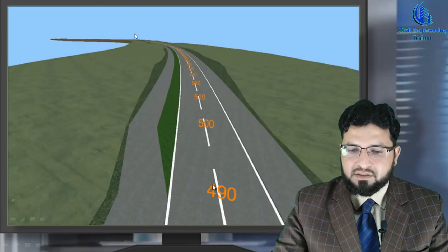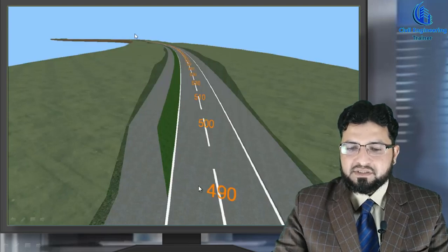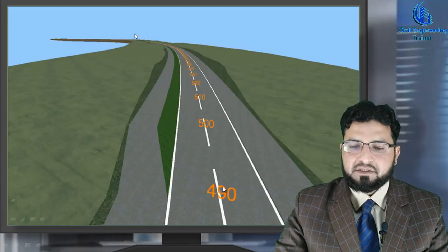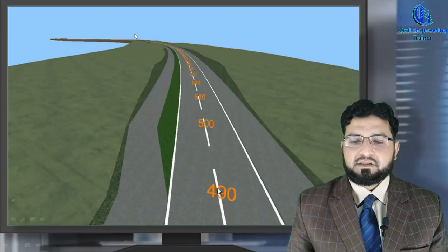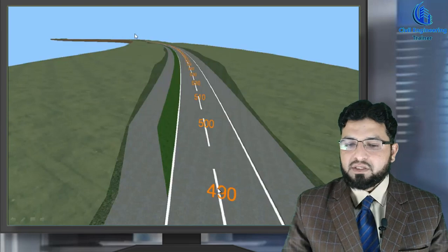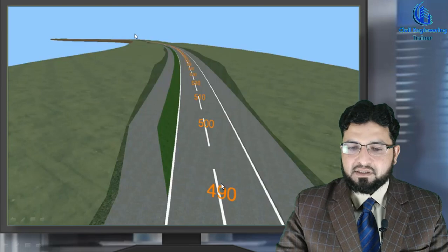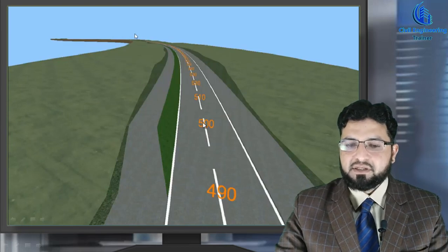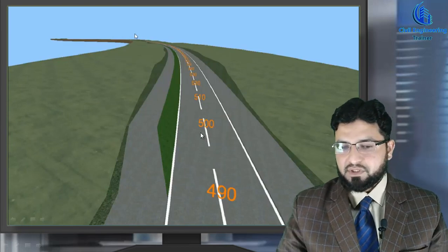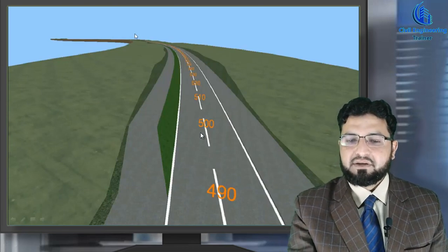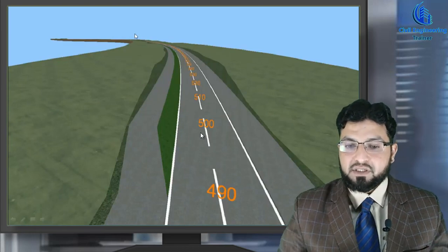Center line. And you can also see some specific values mentioned on its center line. These values are basically station or chainage, okay? Both words are used. What is the main purpose of this? When we give data on site during construction, we give data by the range of station, okay? Suppose we have data about this point like 500 or 510, then we give data on site that this is the level of 500 station, this is the level of 510, this is the level of 520, because we give data on alignment.